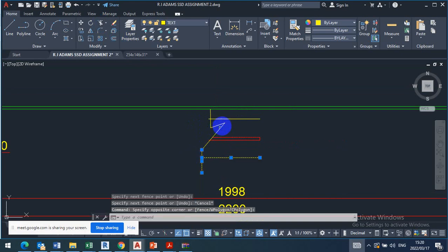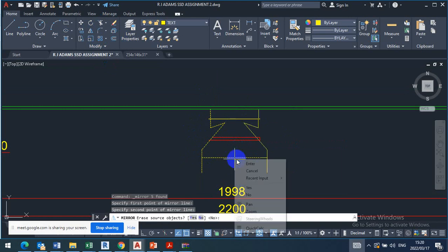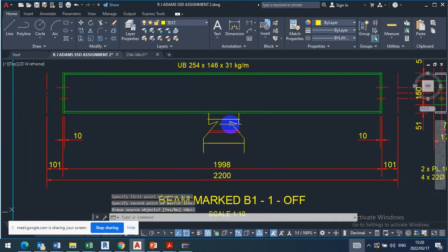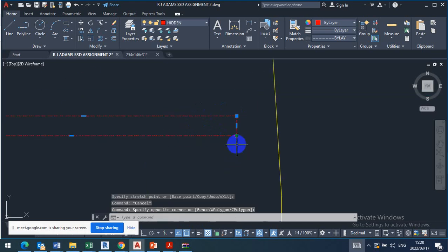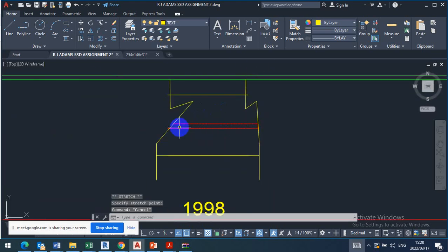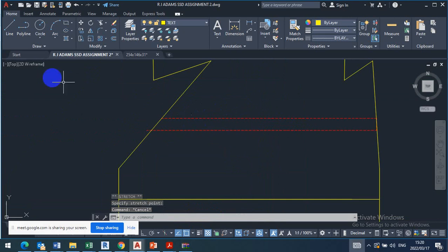Then you're going to offset or mirror this one to the other side. Mirror halfway. But this one should be going to the outside. You just show a cut, and then once you cut, you can show the position of the holes here. How do you show those positions? You go to the tables again. On the tables, you need to know what is the edge distance. Remember, the G1 from the midpoint here.